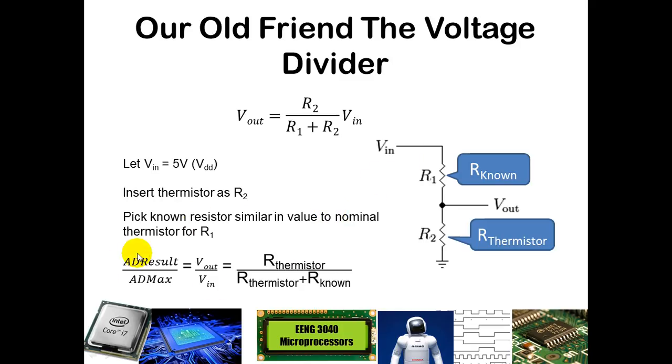We have some math down here that will help us to understand how these circuits work. Basically, taking this and dividing through both sides by Vin, we see that we can get this proportion over here on the right hand side. So we can express the ratio of the output voltage to the input voltage the same way as the ratio of the resistances, as you see here.